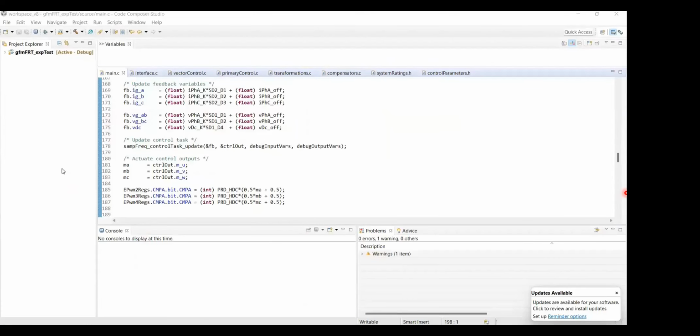So in our hardware test platform, we are using TI DSP as the control hardware. So what I have done, I have taken the code library that I just showed, and I have integrated that into a Code Composer Studio code project. This is the top level firmware source file that you see. This firmware source file calls the different control and background tasks from the software side. And some of the files from the software side you can see here.